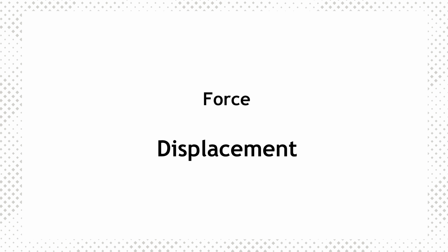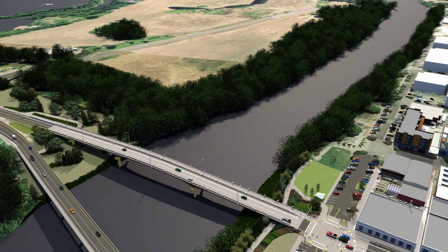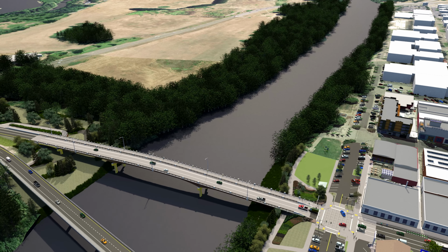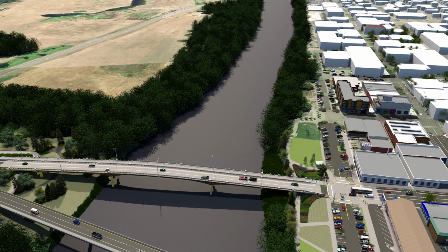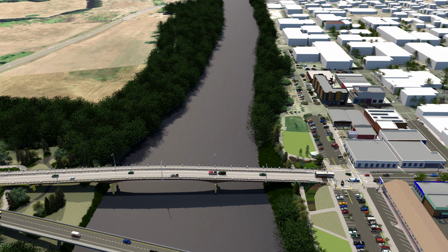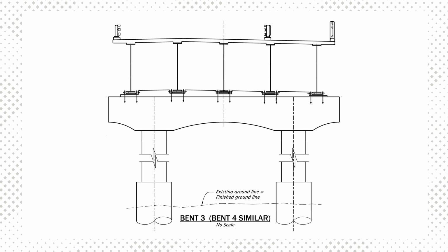be worth implementing. Two primary methodologies exist for seismic design: the force-based method and displacement-based method. The AASHTO specification uses the latter. Both philosophies result in a capacity-designed structure that has sufficient ability to resist seismic forces and displacements. Capacity-designed means certain elements, usually columns in bridges, or beams and braces in buildings, are designed to yield in ductile fashion, and the other elements remain elastic. In bridges, this is often done at the column-to-bent cap interface. The key is to proportion the members such that energy absorption occurs, but the structure does not collapse.